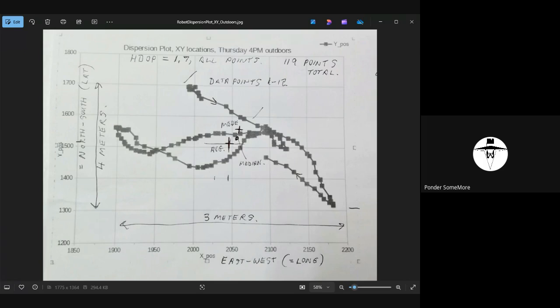And if you're going to do a base station, you actually want one of the survey grade antennas. They have their built-in ground plane, and they're slightly nicer. How much might something like that be? I think it's $120 last time I looked at SparkFun. That's doable. They're a bit heavy for putting on most robots, but that's the kind you would see on a large tractor.